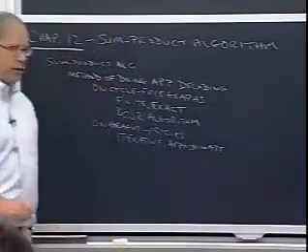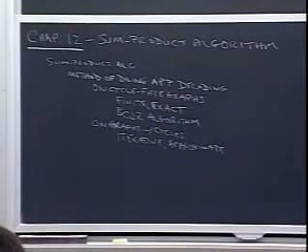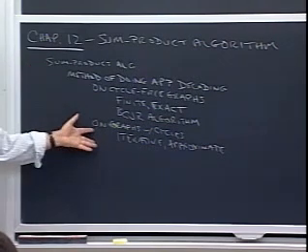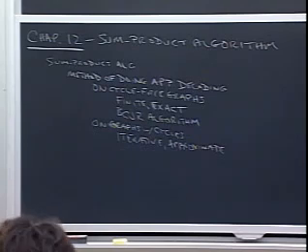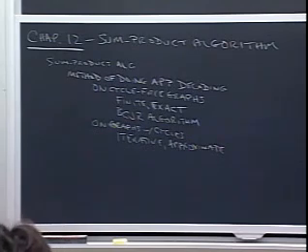For instance, when I said that decoding of that simple little reduced Hadamard transform realization for the 8,4,4 code, which had cycles in it, I said it was a couple of tenths of a dB suboptimum. That was obtained by running this algorithm on that little graph with cycles until it seemed to have converged to something and plotting its performance.